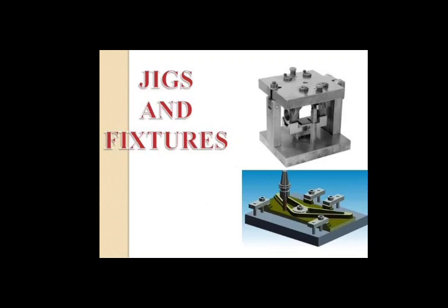Forces and moments should be balanced so that the workpiece will remain at rest. It is very much true. Balance of forces and balance of moments is required to achieve linear equilibrium and rotational equilibrium respectively. Yes, we all know this fact. The equilibrium can be achieved with the help of clamping devices and locators. Clamping devices provide holding forces and stationary locators are used to balance those forces. This was the first theory you have to understand, the equilibrium theory.